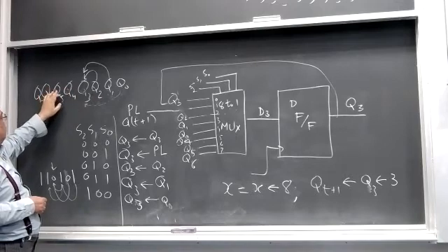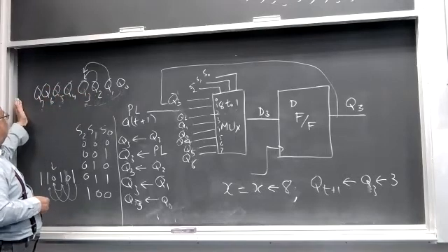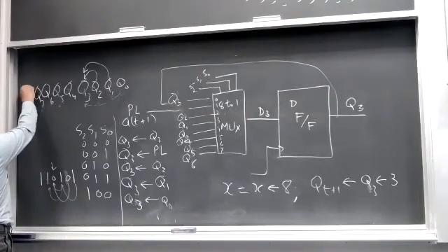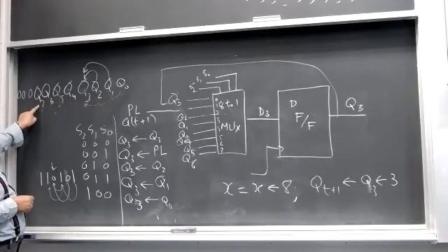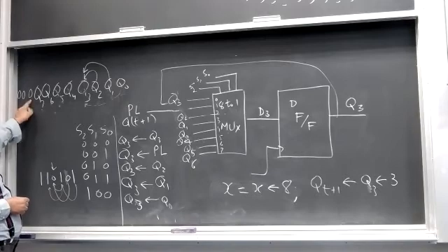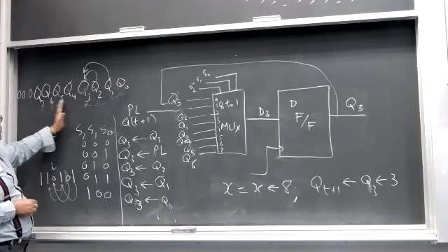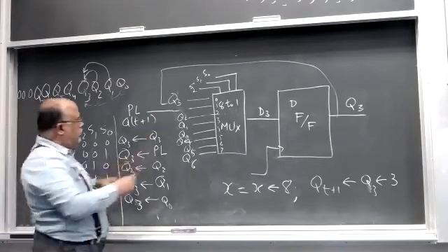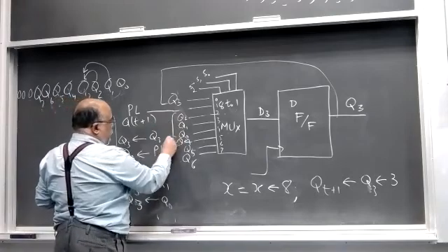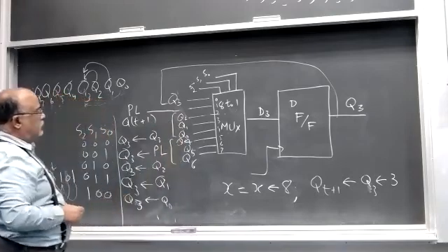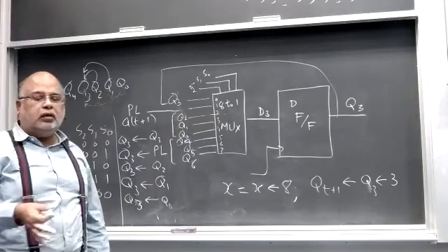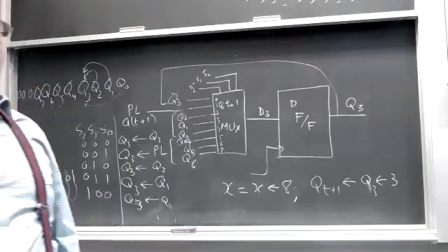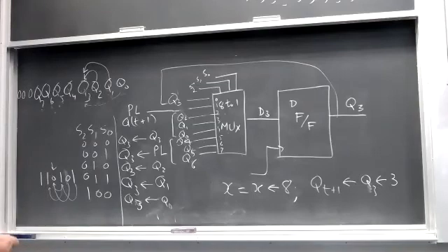Same case with Q5, you can think about 3 neighbors on this side and 3 neighbors on this side. Here you have zeros already installed somewhere. So into Q5, either Q6 or Q7 or 0 can go, if you are shifting right. Every one has access to 3 neighbors on each side, 3 neighbors on the right side, 3 neighbors on the left side. So it can move any value in the next clock cycle. For Q3 and also for Q2, there will be 3 values like this, for Q1 also 3 values, and for Q0 also.